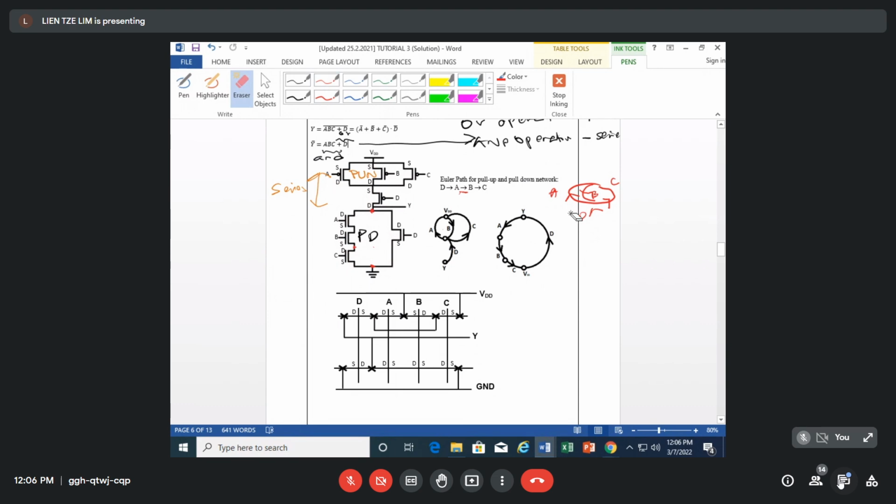Okay, in the schematic diagram here, the A, B, C source terminals are connected to the VDD. Here A and B are adjacent, so the terminal here should be labeled as source. That is connected to the VDD. And then here also another source terminal connected to the VDD. After we label the source terminals, here we know that it is a drain terminal.